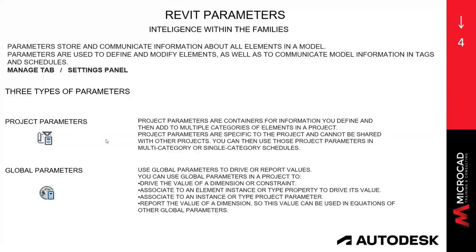They are very cool because, let's say you apply a project parameter to your windows, and then for whatever reason you go to the Anderson website and you bring in an Anderson window to your project. Because you created that parameter as a project parameter that is applied to windows, the minute you insert that window into your project, it will get that parameter. And that is very cool.